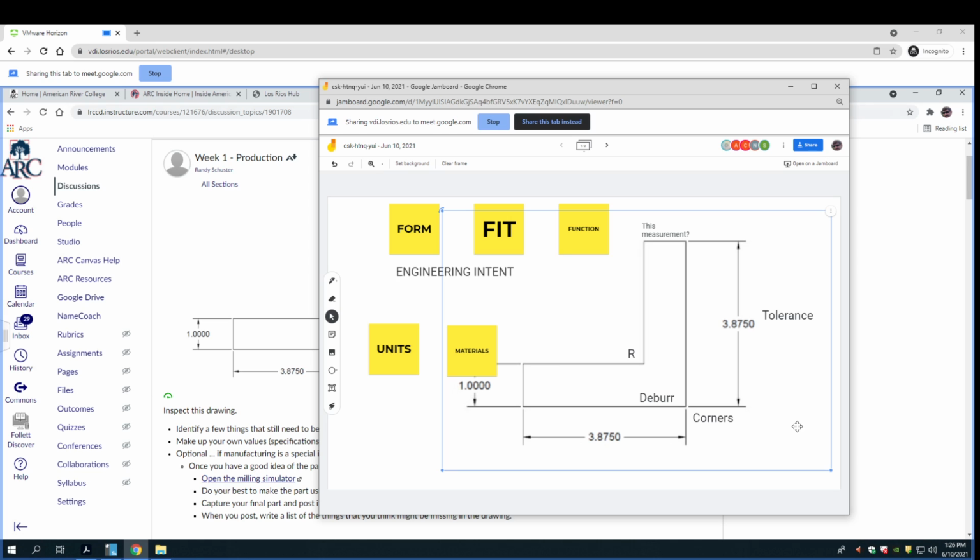And in civil drawings, you have to claim it somewhere in your drawing package. Interior design, sometimes, depending on if you're trying to fit into an existing space or not. Interior designers usually use max and min instead of like a plus or minus. But everything needs a tolerance.